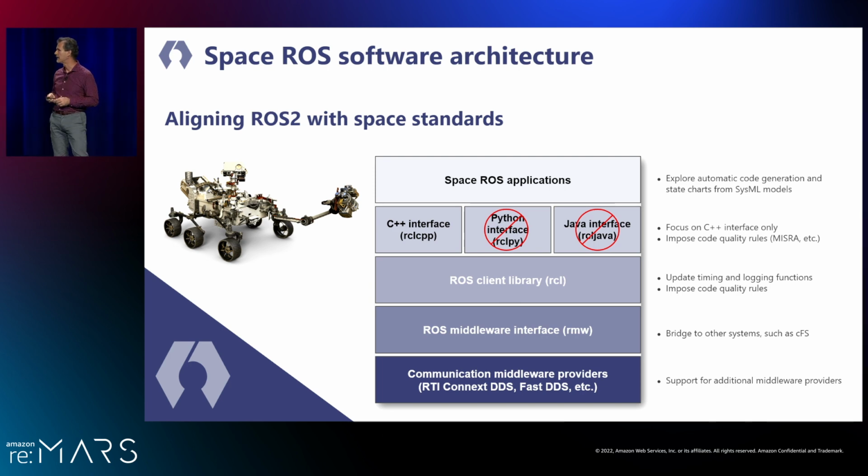So there's the layers of the ROS stack, if you're not familiar with it. As I mentioned before, at the core, there's a middleware provider, and that's abstracted by a so-called RMW interface, the ROS middleware interface. Being an abstraction, you can then plug in different providers. That layer is pretty heavily influenced by DDS, and it's designed so that DDS can plug in, but it doesn't have to be DDS. There are implementations of the middleware that are non-DDS implementations.